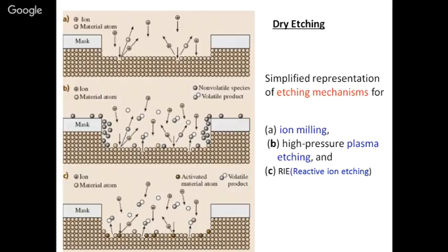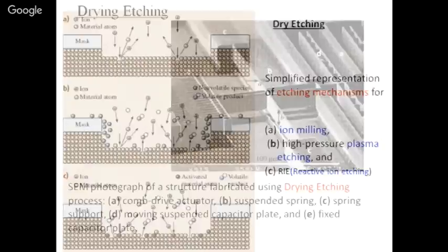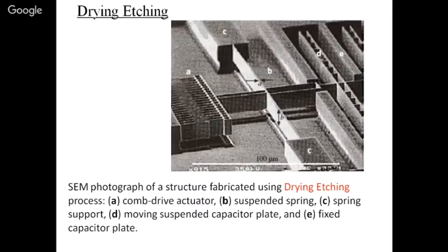Here, ions are formed by knocking electrons from the atoms and are accelerated in an electric field, which collide with the work surface and reduce the atomic force between the molecules and convert into atoms, and the atoms can be liberated or removed from the hard or solid surface. This is how a microchannel can be manufactured.